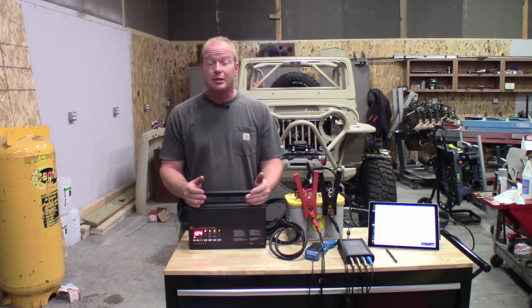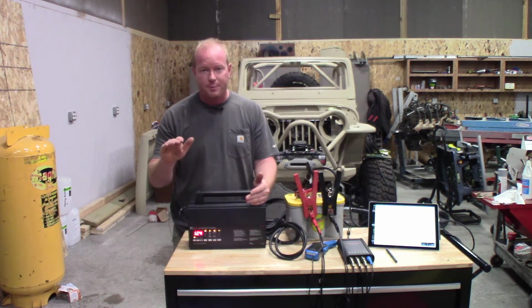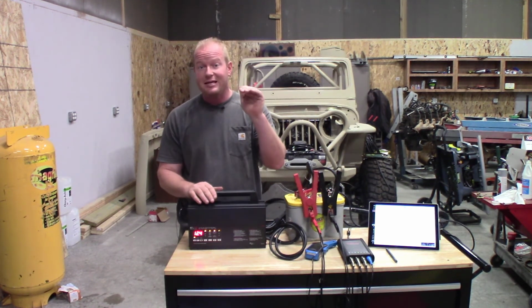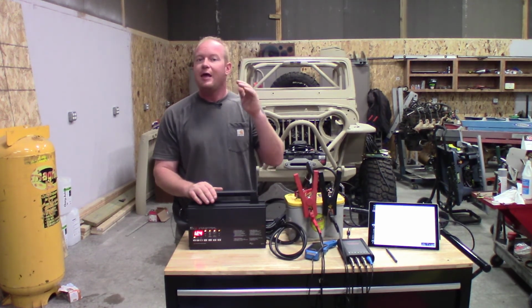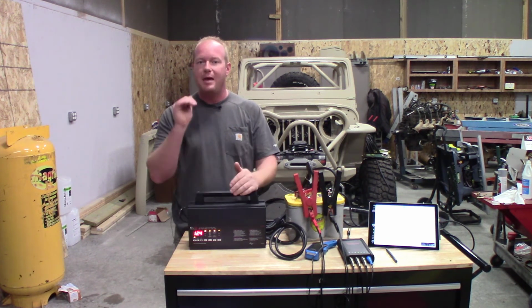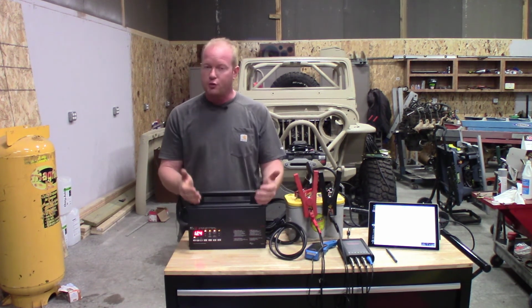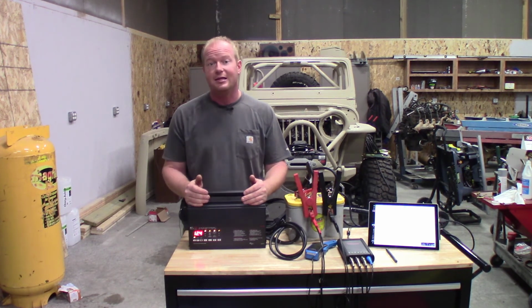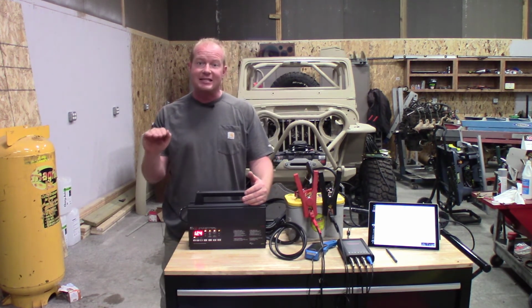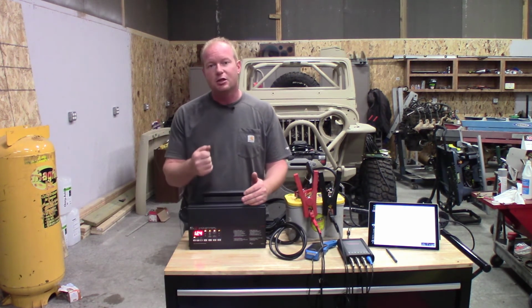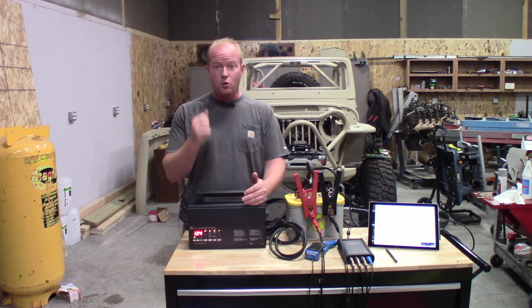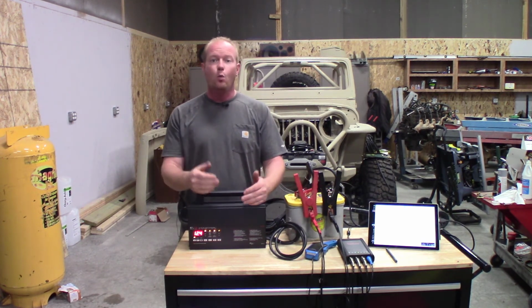This has the ability to maintain a stable power supply up to that 70 amps. So the voltage will stay consistent and the amps will do whatever it takes to maintain that voltage. Also, you're not going to get any ripple effect out of this. So it's a very clean and stable voltage. So this is the choice you want to go to whenever you program a vehicle with your J-Box.